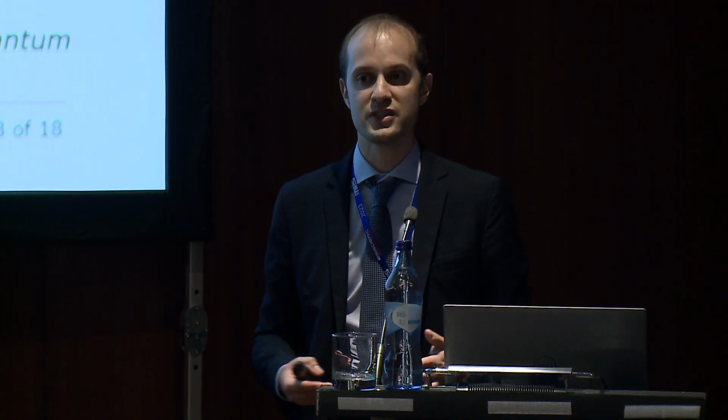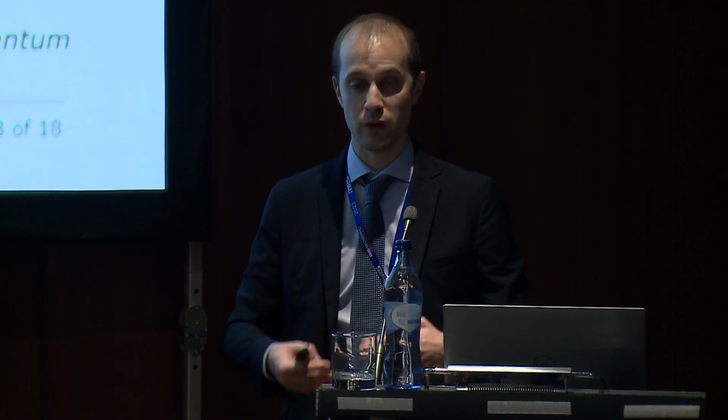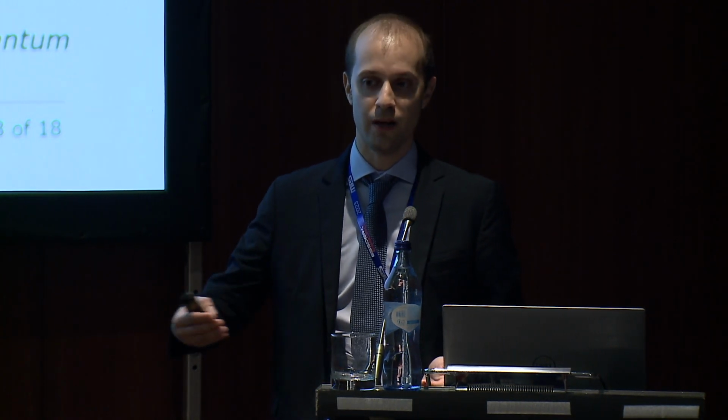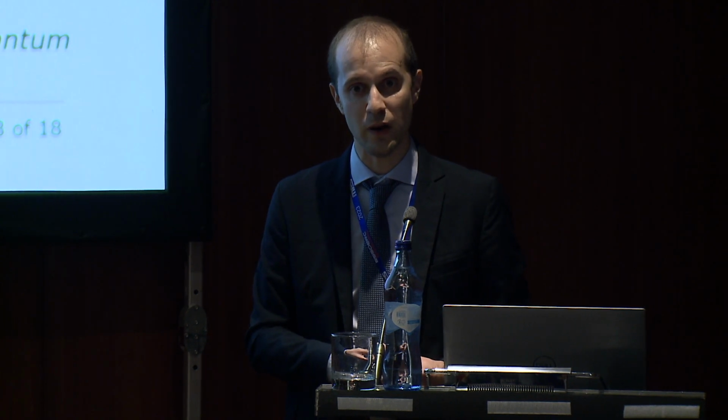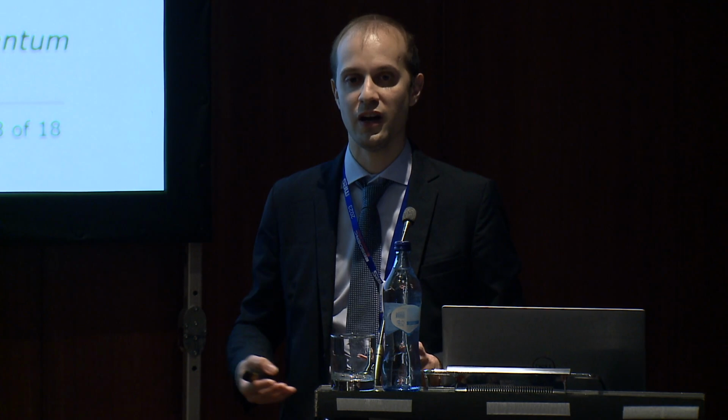And the goal is to reach systems that have a scale in terms of number of qubits so that you can solve useful problems. And this is going to set a challenge on the electronics side so that you can meet the power budget which is allowed by the dilution refrigerator. So we're speaking about orders of magnitude for current systems as a target of 1 milliwatt per qubit.